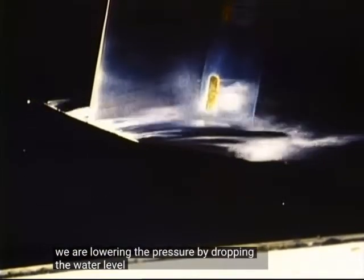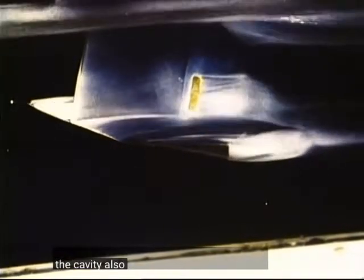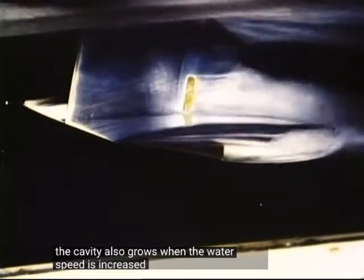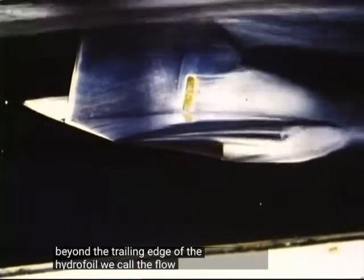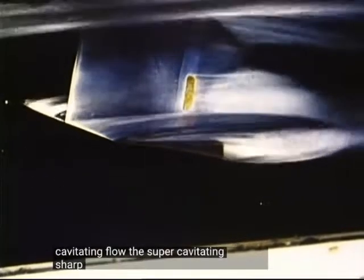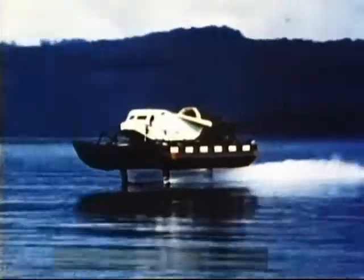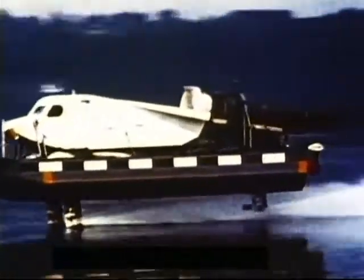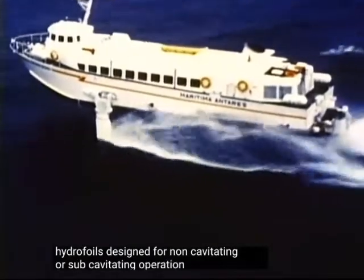We are lowering the pressure by dropping the water level above the foil by means of an upstream sluice gate. The cavity also grows when the water speed is increased. When the cavitating region extends beyond the trailing edge of the hydrofoil, we call the flow a supercavitating flow. The supercavitating, sharp-edged foil is a type used on very high-speed hydrofoil boats, such as this 80-knot boat. Hydrofoils designed for non-cavitating or subcavitating operation are used on hydrofoil boats at speeds below about 50 knots.